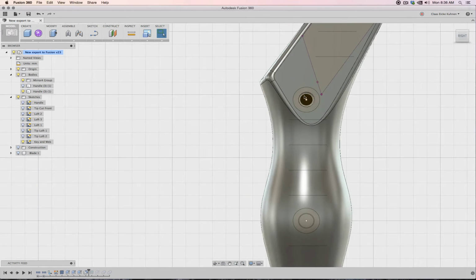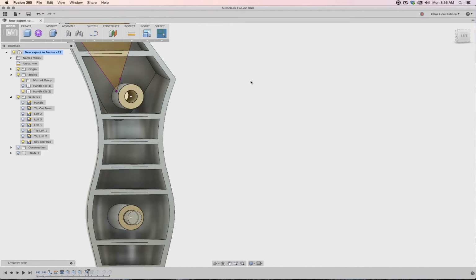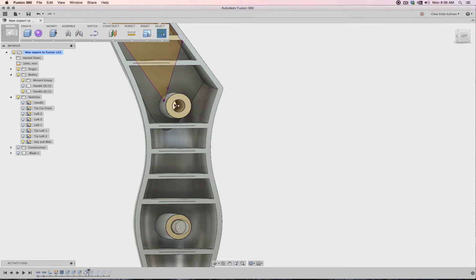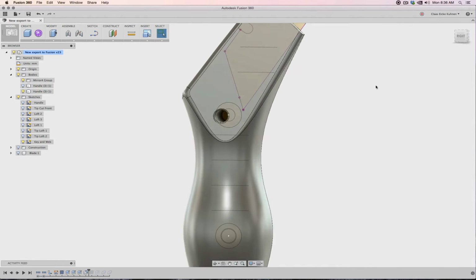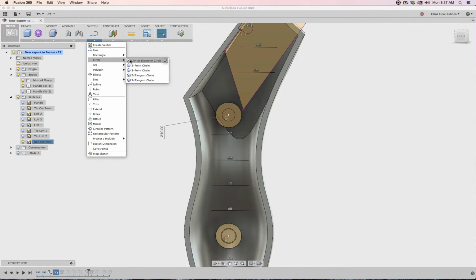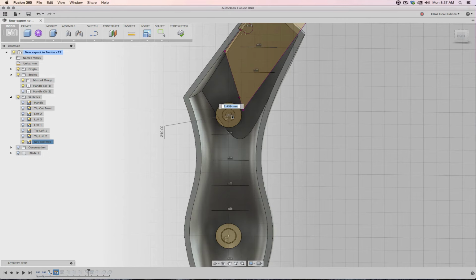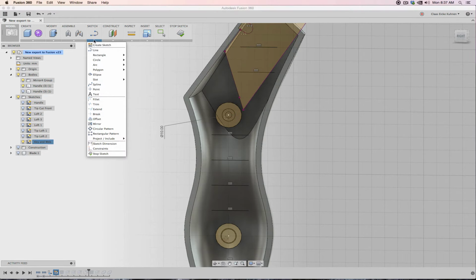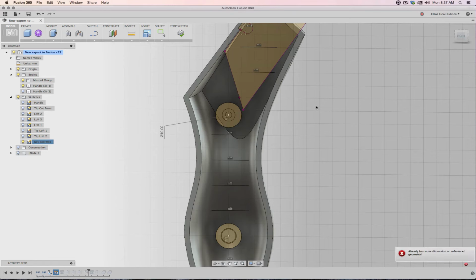So currently we can put a complete screw through here, but let's say this is as wide as, for example, the head is. So it would basically fall into the other side, which means there are two strategies now. Either we make this material much thicker, so we can bore out the paths for the screw head to fit through here, in case this opening should represent the width of the screw itself. Or what we simply can do is I go into here, edit, sketch, and I'm just going to create another circle there. Let's say, I don't know, 2.5. I'm just eyeballing visually some things here. Don't forget to nicely dimension all that stuff.